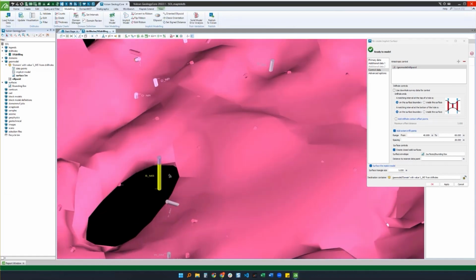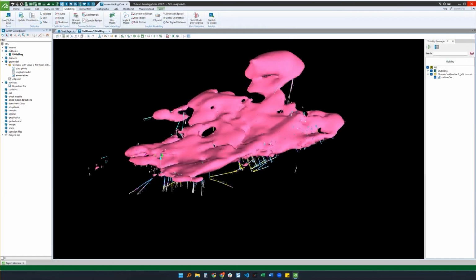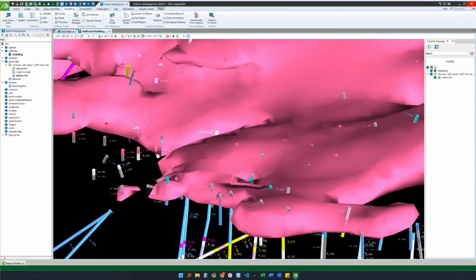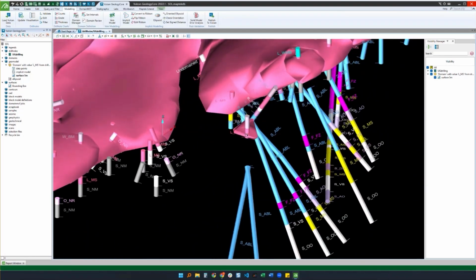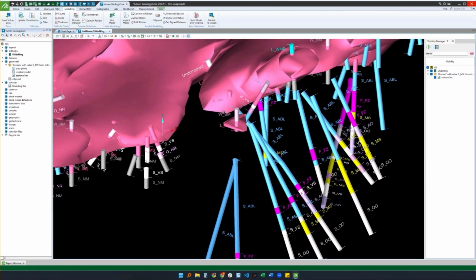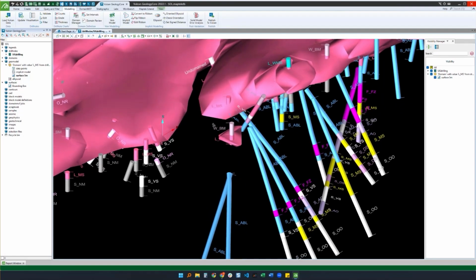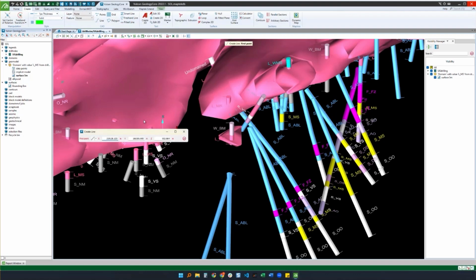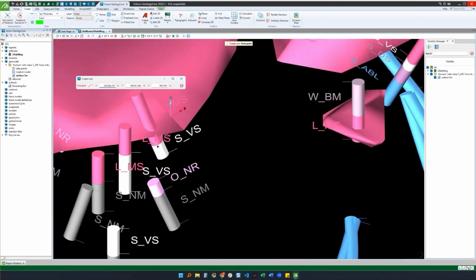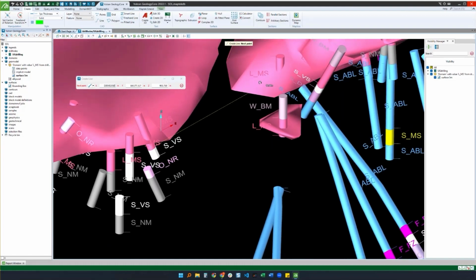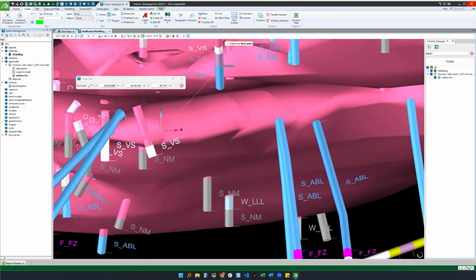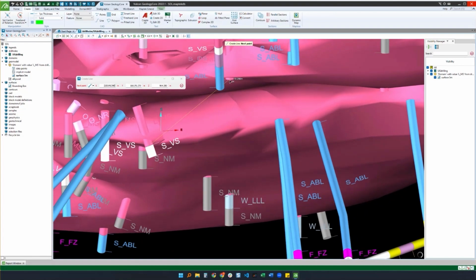except for where we expect them to be, really, when we've got a different domain. Now if I want some finer control over what the model does in certain areas, I can add additional data like ribbons to control that. So if we find a spot that we want to edit, so I might want to join these two bits up, for example, through here. So to do so, we can just create a line. So I will create my line from there to there.